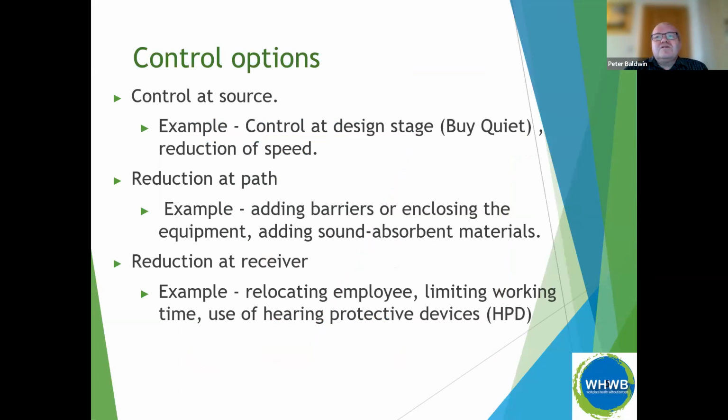So we've talked about this, and looking at the control at source, reduce the amount of noise that's being produced. Design it out. Do you need to do a noisy process? Is there some other work method you can use? I mentioned welding as opposed to bending metal. It's a very, very good control. Then a buy quiet policy. When you're buying machinery, look at the amount of noise it produces.